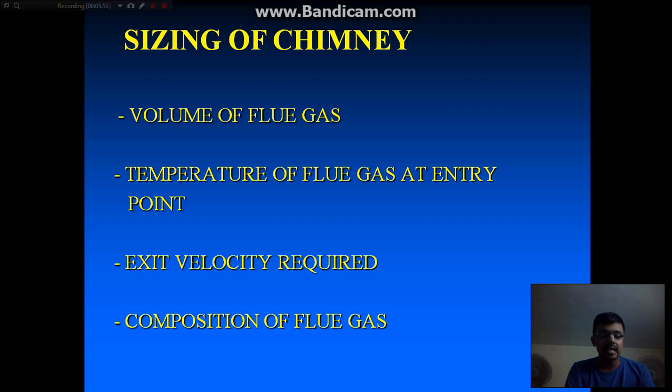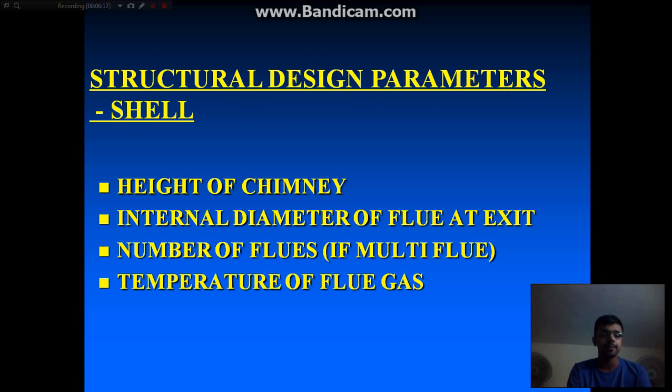The third is the exit velocity required, because it is essential at the upper end, which is the free end, to have the required capacity. The fourth is the composition of the flue gas, because the composition of the gas exiting the chimney will decide the materials of our chimney as well. So it's very essential to have these four points for the sizing of a chimney.